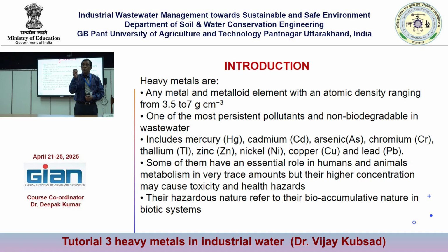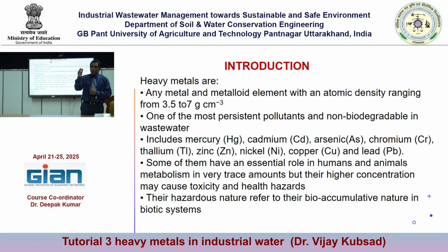That's why we are very cautious when we are accepting an industrial wastewater. We make sure that that is treated properly and then discharged. However small it is. That is, if the common effluent plant belongs to this location, then if there are industry, metal industry or any other industry which contributing this kind of heavy metals, then you want to have a local limits.